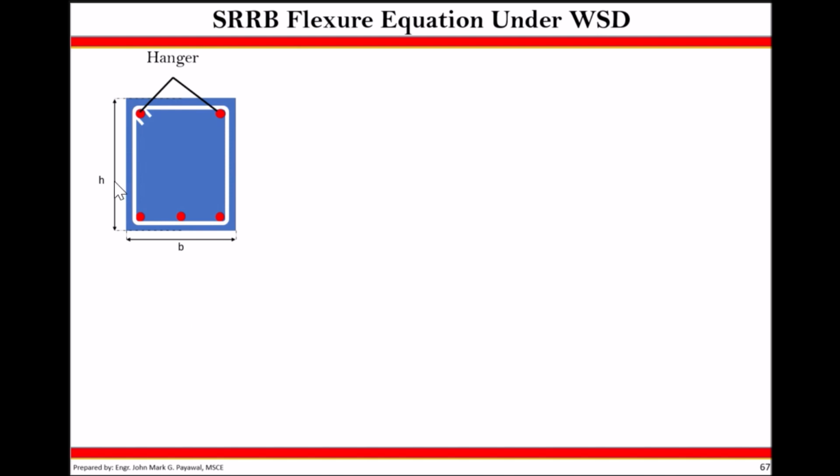We're given a typical sample of your beam detail wherein we assume and take your reinforcement at top to be a hanger. We will label B as hanger, meaning there are no stresses at the top members. Only the reinforcement at the bottom are carrying tensile force, which results to Fs or the stress on your steel.